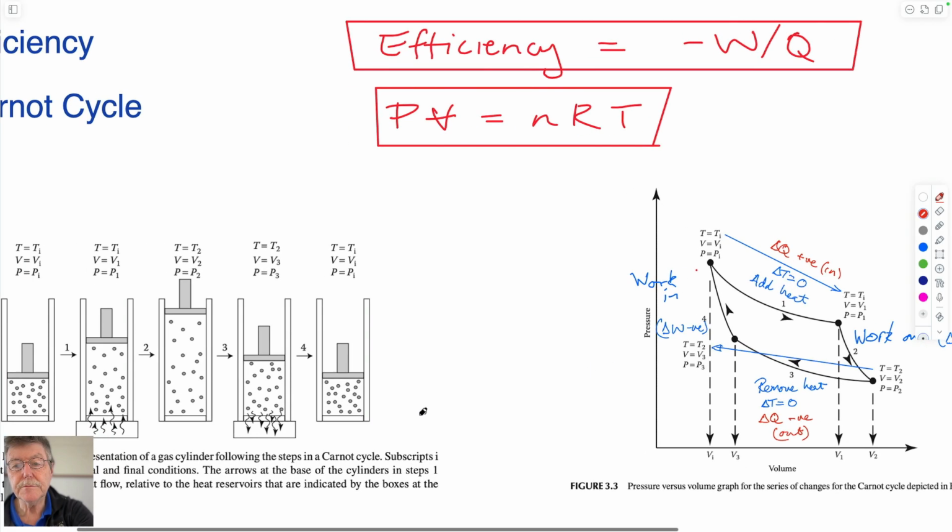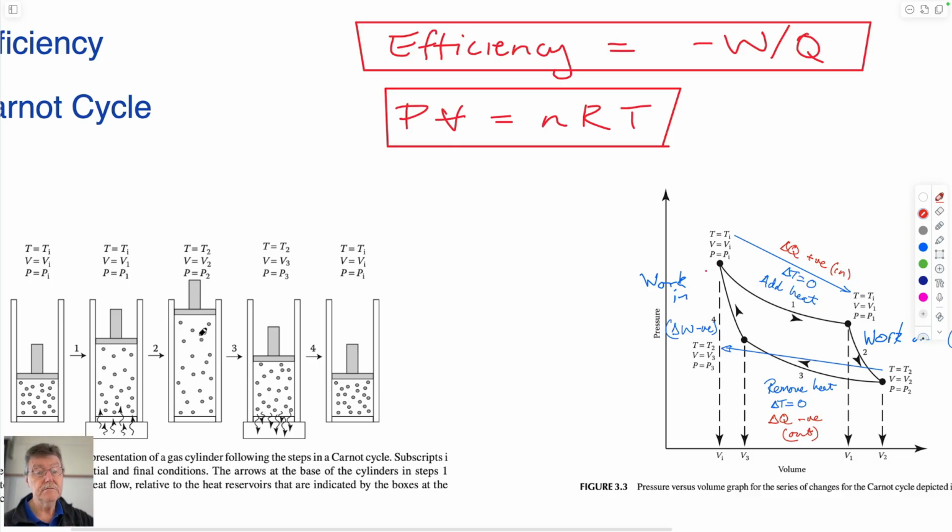And this comes out of Glassley's book, which I looked at yesterday, available free online. And this is the Carnot cycle going from a compressed fluid which has small volume, present here, allowing it to expand by gathering a small amount of heat. So this is the change in heat input in the system. It's positive because it's into the system in our sign convention. And this allows it to gain enthalpy.